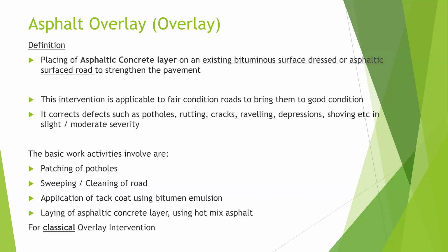Now, when the road becomes so poor, that is having all the ratings so high for all the defects, the distresses, then overlay will no longer be applicable. Now, the overlay is supposed to correct defects such as potholes, rutting, cracks, raveling, depressions, and these are supposed to be slight to moderate severity. Immediately it becomes extreme and extensive, then overlay will no longer work.